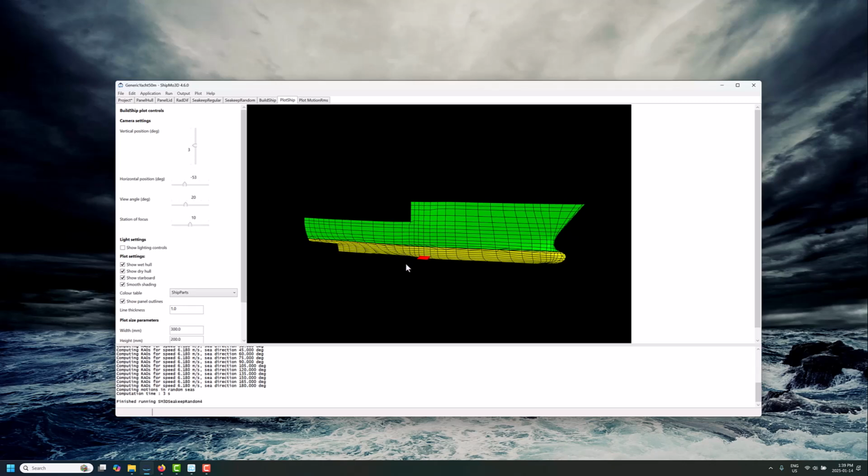This control mode is purely sinusoidal actuation. What that means is that in some cases, commonly available fin stabilizer equipment that works at zero speed uses a completely different kind of control methodology. They actuate them more like in a paddling motion, which uses a different approach to create the hydrodynamic forces to slow down the roll motion of the ship.